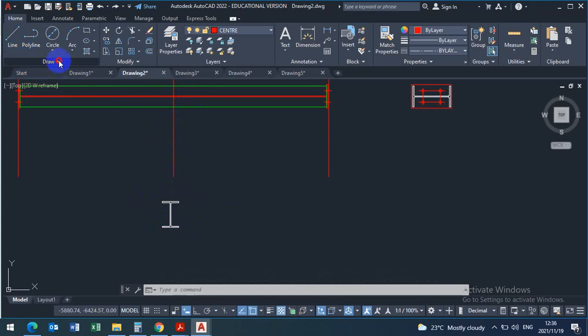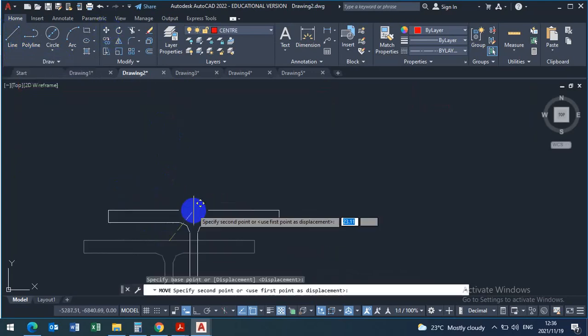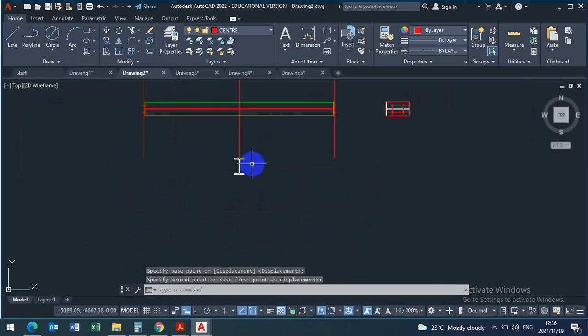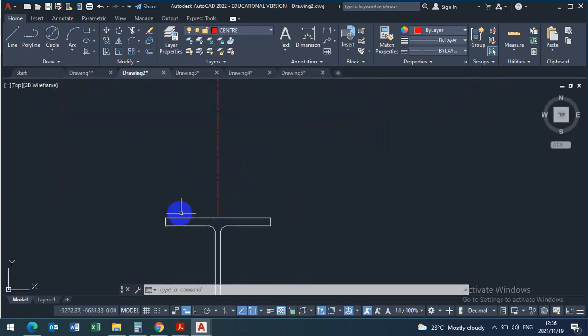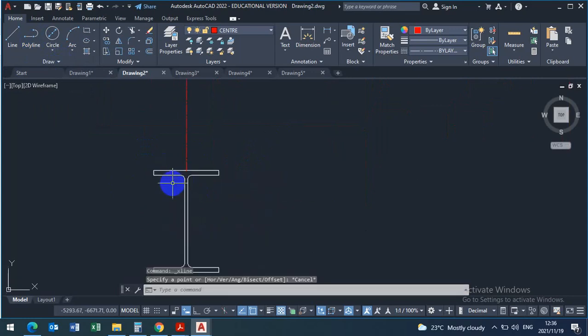So what you do, you are going to center it with a center line, maybe here. If it's sitting like that, we are going to see the webs from the front only, not from the top. So here it's the top view. When we're looking at it from the top view, you are only going to see the top of the flange here. You can try to project, which is not necessary. What I only need is to show the hole position on the beam here. The hole position will be, you offset the gauge distance using this center line.